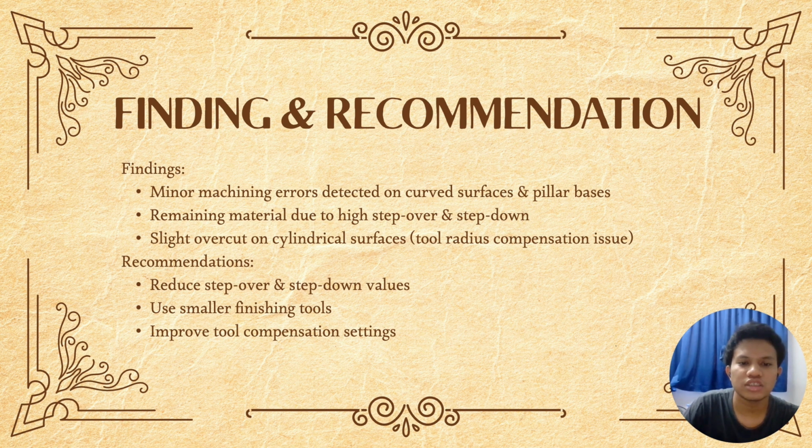To improve the issues, there are several recommendations. Firstly, reducing the step over and step down values will help improve machining accuracy and surface quality. Secondly, using a smaller finishing tool is recommended to achieve a smooth surface for complex geometry. Lastly, the compensation settings should be properly adjusted and optimized to ensure better dimensional accuracy in future machining processes.